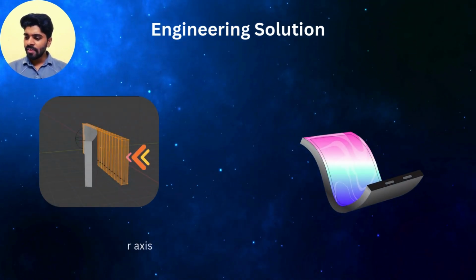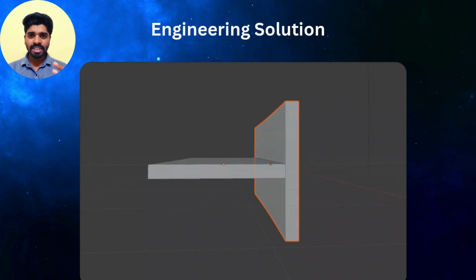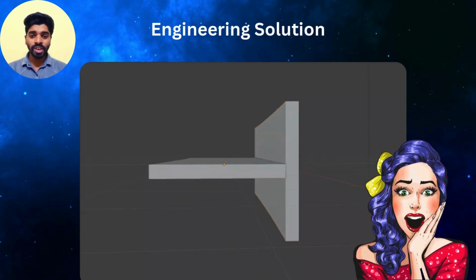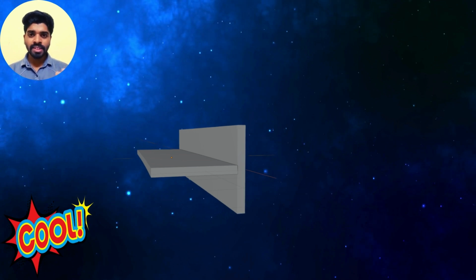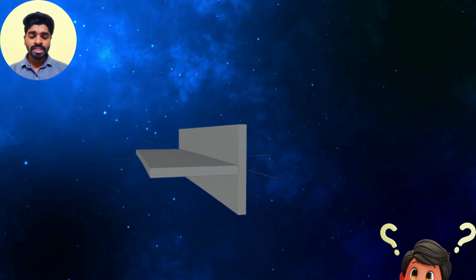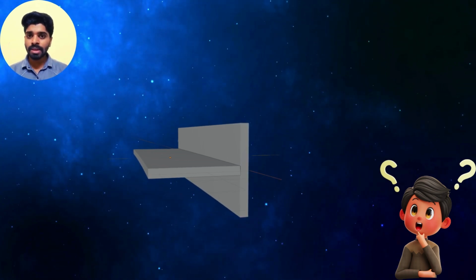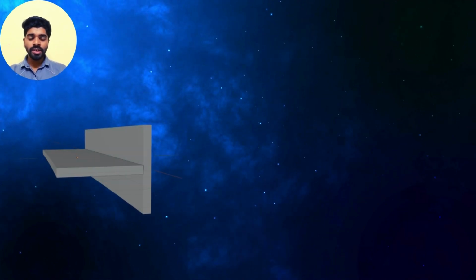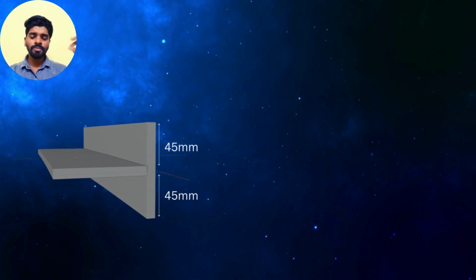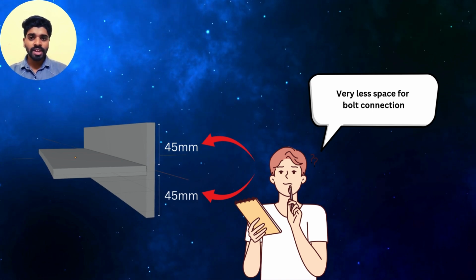We can do one thing. We can put another plate oriented in another direction. Since its strength is in the major axis, we are using its strength for the weakness. Now this shape can easily resist bending in both axes. But there is one small problem with this. Since the depth of the member is around 100 mm and if you want to connect this with bolts, then there should be enough spacing for the bolts. As of now, on both sides only 45 mm space is available. So more than 12 mm bolt size we can't use.